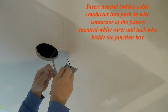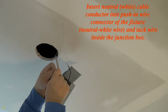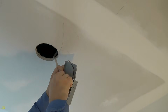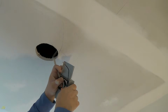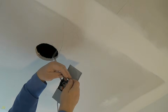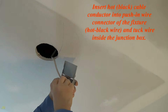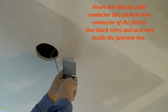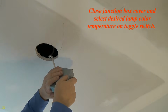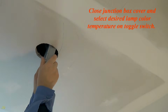Insert the neutral, white cable conductor into the push-in wire connector of the fixture, neutral white wire, and tuck the wire inside the junction box. Insert the hot, black cable conductor into the push-in wire connector of the fixture, hot black wire, and tuck the wire inside the junction box. Close the junction box cover and select the desired lamp color temperature on the toggle switch.